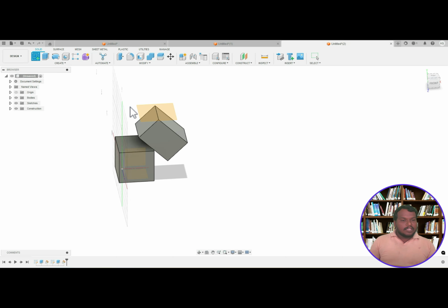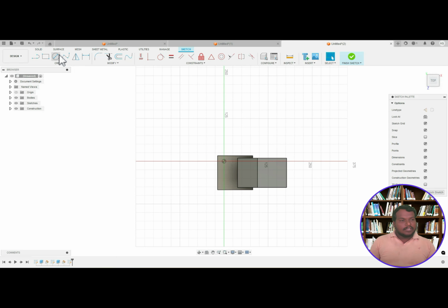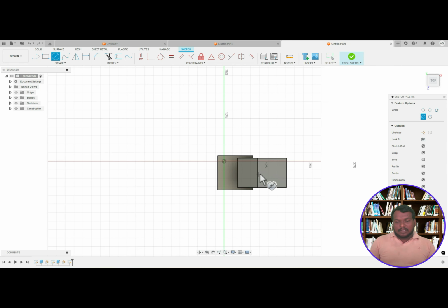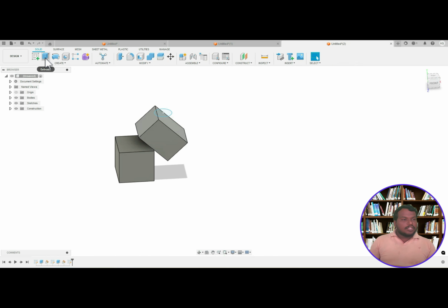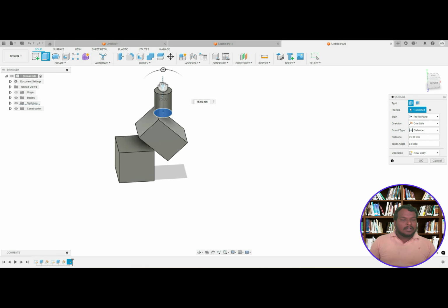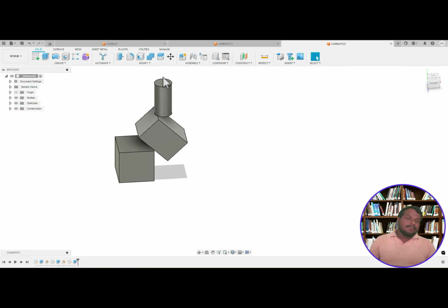Go to create sketch. Click on the sketch. So I'm drawing here a 50 mm dia. Okay. Finish sketch. Next select it and draw it. The 100 mm. Okay. If I select the angle, we'll see that.